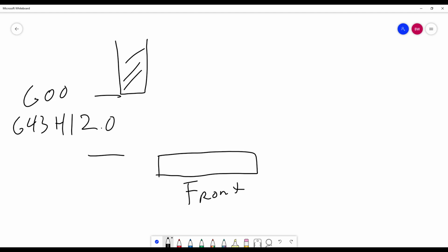You will probably rapid or feed to like 100 thou above the workpiece. I will rapid usually. I like that little break. It's a good idea to check your tool comps that way. But whenever I'm going Z negative, I try to use a G01. Typically it's slower. Okay. G01, again, like I said, requires a feed rate.